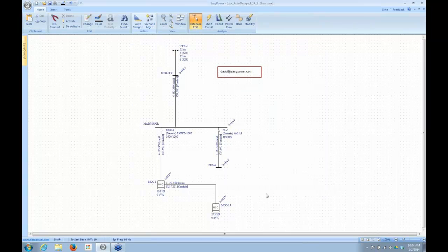And in the emergency mode, you can just close the file without saving any of the changes since you started running AutoDesign, and those should be discarded unless you have autosave turned on. So that's something to keep in mind. If in your options you selected the autosave, then you may want to be a little bit careful about combining that with the AutoDesign.